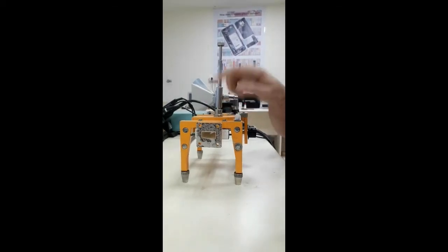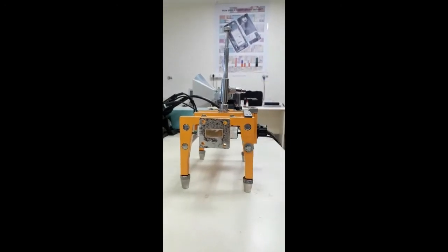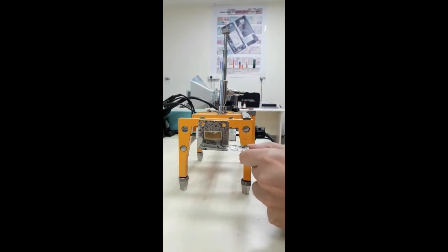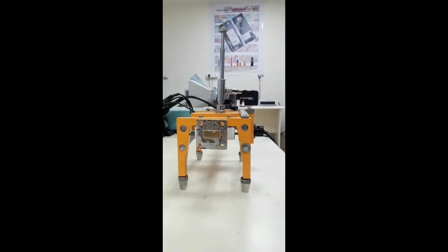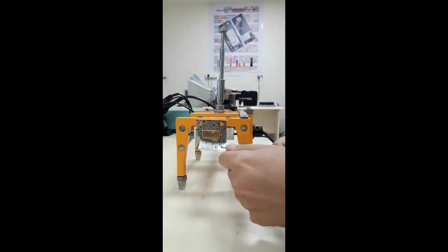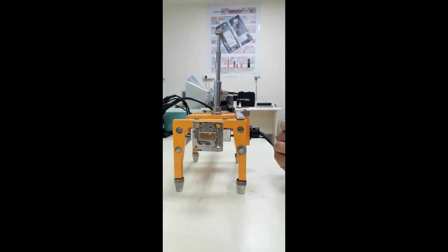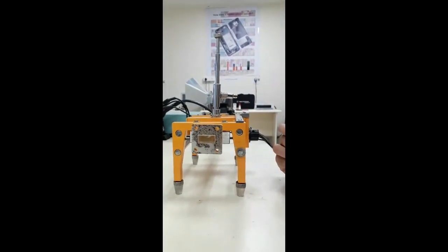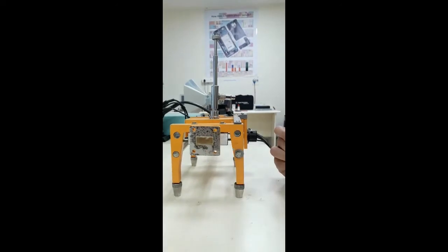Now what you can see is this transmission line as part of the slotted line is actually made up of a rectangular waveguide. So if you take a scale and measure its A and B, that is the horizontal and vertical dimensions, you will see that this is roughly about 2.286 centimeter by 1.016 centimeter. If you are not able to remember these dimensions in centimeter, it's very simple. Just remember these dimensions in inches. This is about 0.9 inches and this is about 0.4 inch.